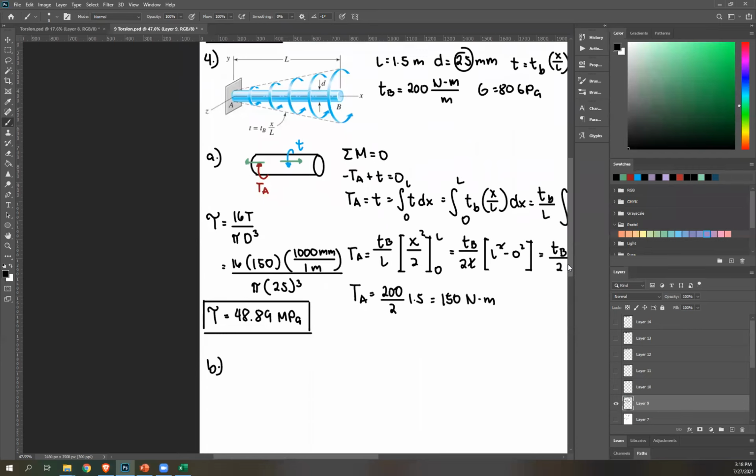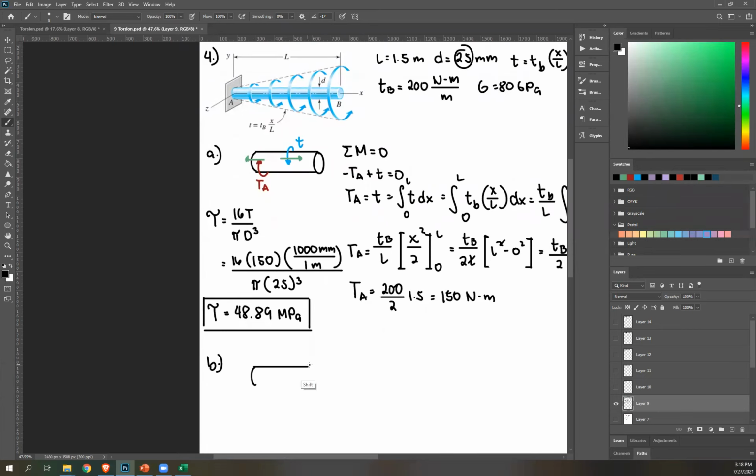So in order to do that, let's isolate again another method. So this is still the same. There's still EA over here. Your torque is still here. And then the difference is we're gonna cut this at a distance from A. So this will be length X. Okay? And then cutting it at a section, there's gonna be an internal torque. So internal torque, again, assume distance. I'm gonna assume this way. So let's call that internal torque for AB.